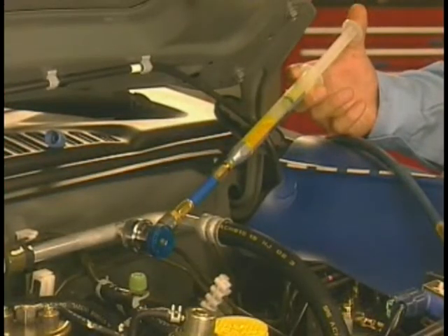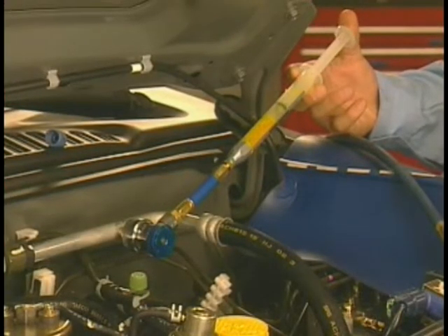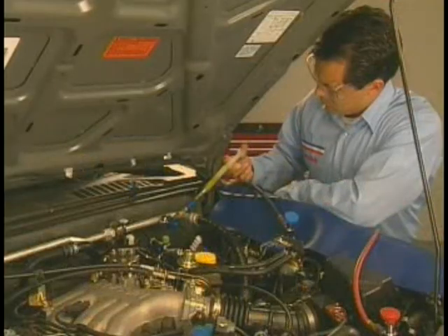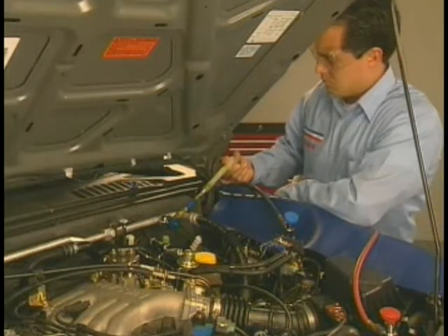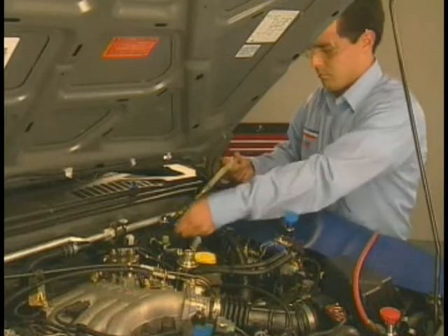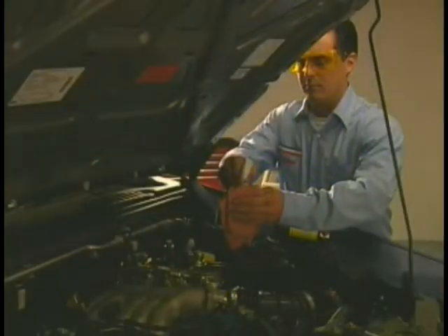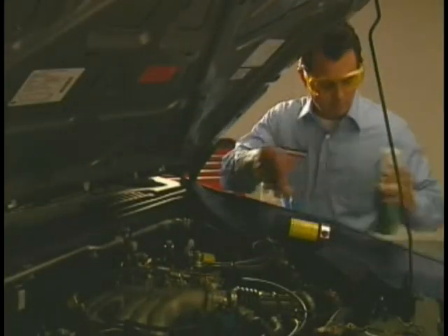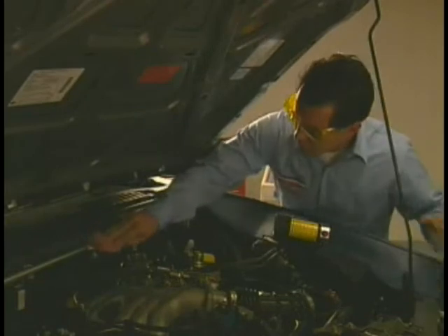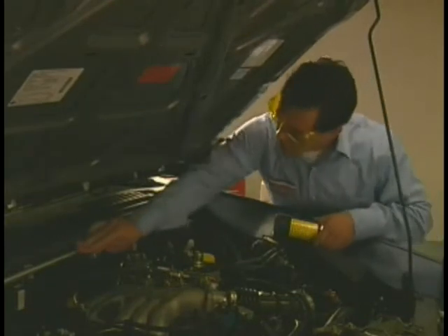Fluorescent dye detectors have come into wide use. Follow the tool manufacturer's instructions to inject the dye into the systems and allow the air conditioning system to run to circulate the dye. A black light is used to check for the presence of dye that has leaked out. Be careful when working with the dye and make sure none of it gets on painted surfaces, as it will stain the paint.